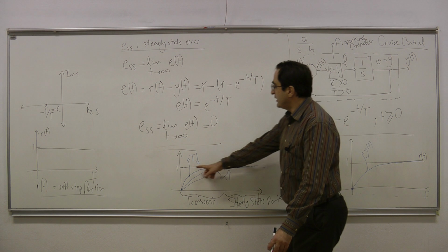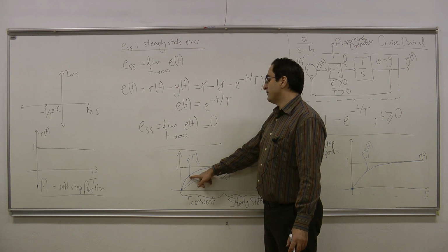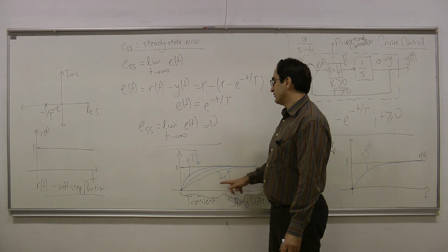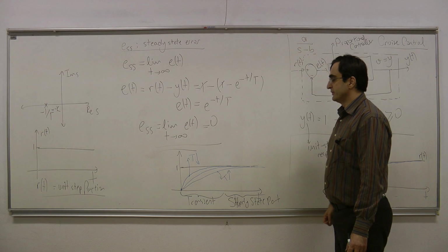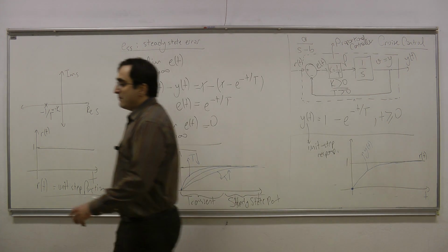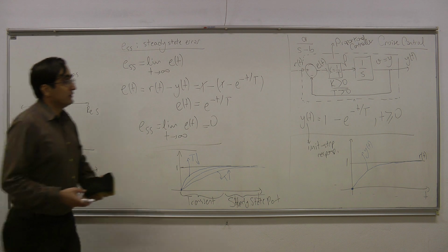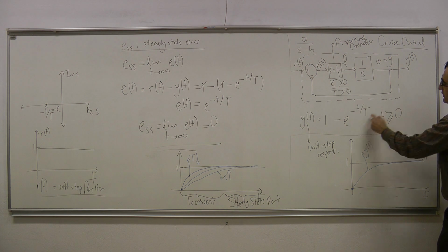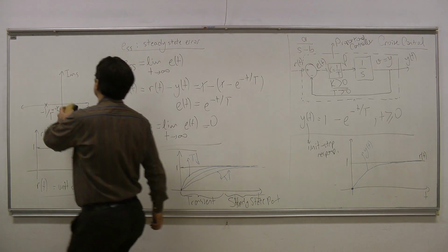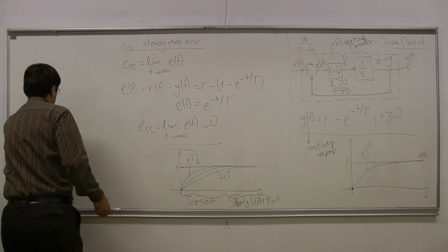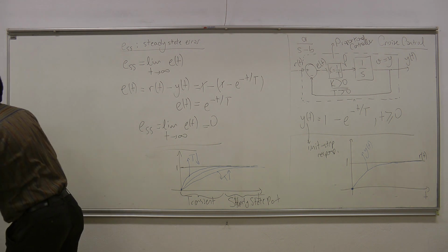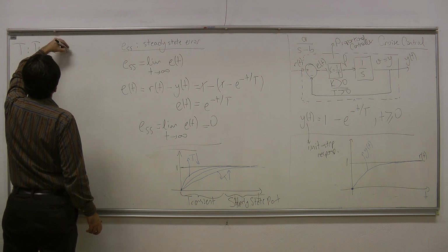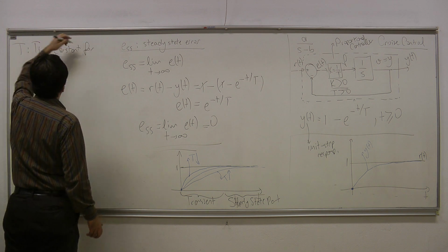And if t becomes smaller, then we have a faster control system. The convergence becomes faster. If t is larger, we have a slower control system. So this parameter capital T, which scales the small t in the exponential, is called the time constant for the system.